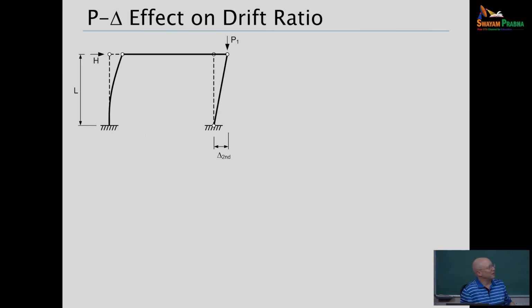So now let's get a little more fancy. Now we've got a cantilever with some other parts of a structure that are tied to it at the top of the cantilever. It's just a pendant strut that's tying it to a column over on the right. Column over on the right is what we would call a leaning column because it's pinned top and bottom. And so if I took away the strut, what would happen to the column on the right?